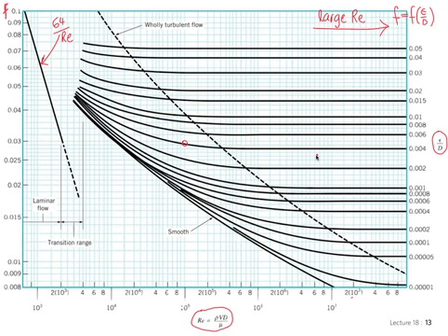And what we read here we call a friction factor, not a friction force. It's a non-dimensional factor. It's a shear stress that has been non-dimensionalized. We could check the units of that.